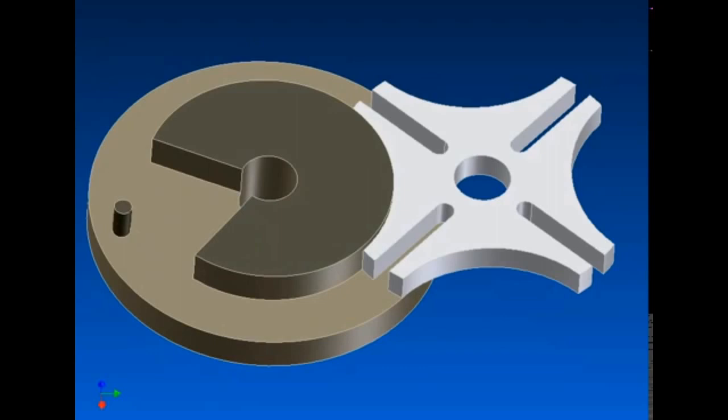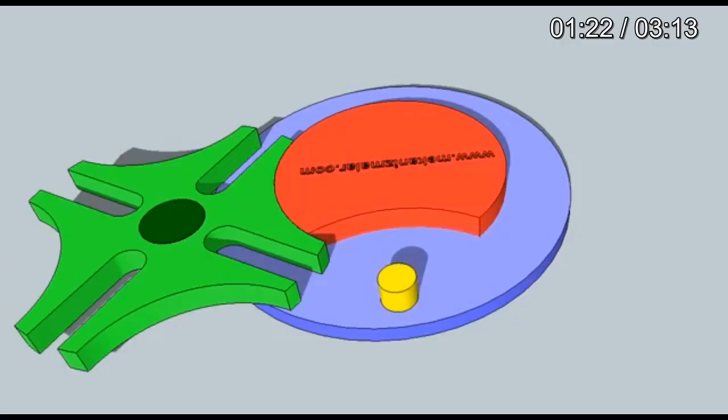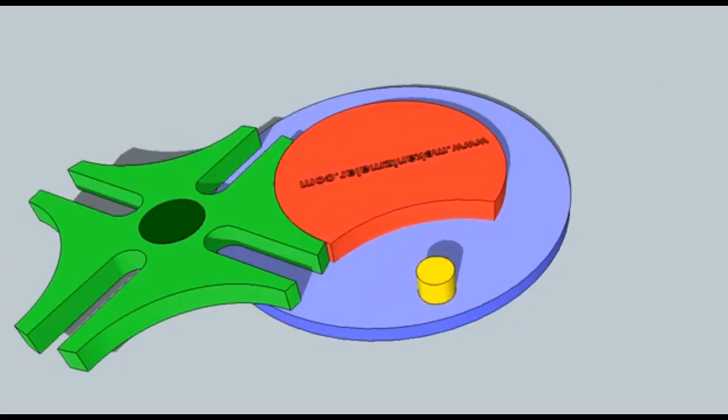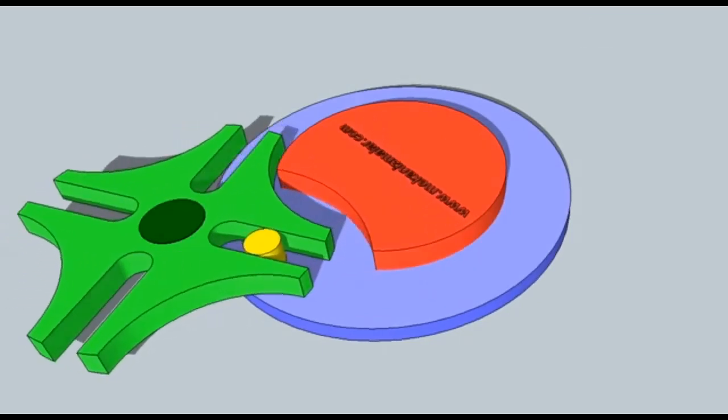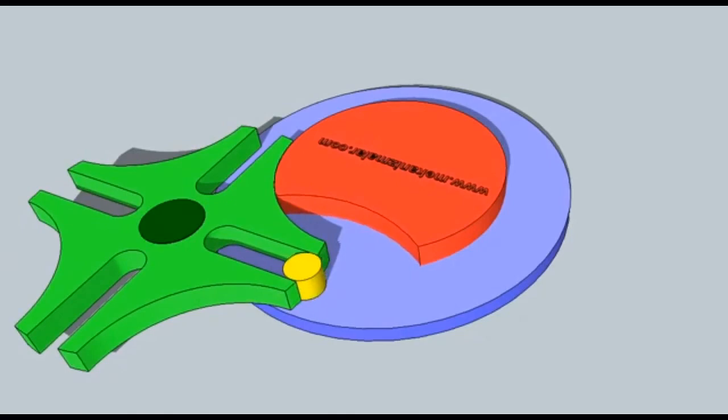You can think of products being manufactured in a line, for example bottle manufacturing. The bottle is required to be stationary to do some operation on it for a moment, and then it has to move to the next stage. It has to be stationary for some time, then move again, then stationary again. So this is a discontinuous motion, the Geneva wheel. Here is another video showing how a Geneva wheel can be created.